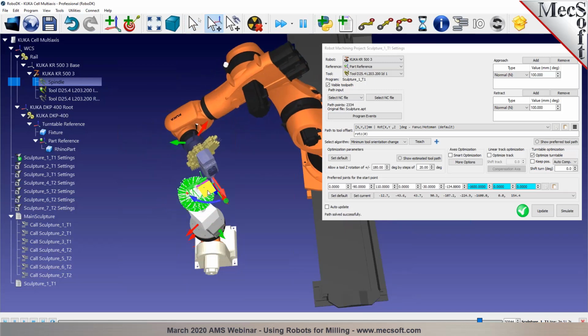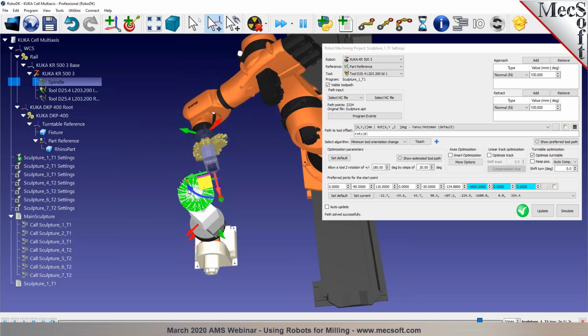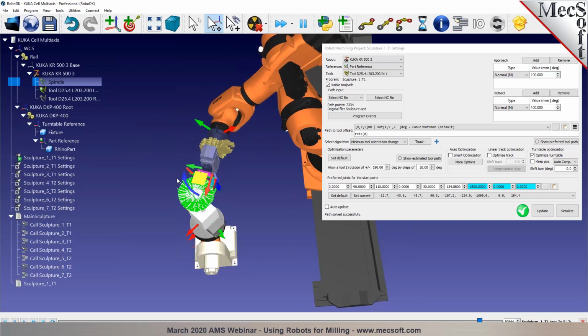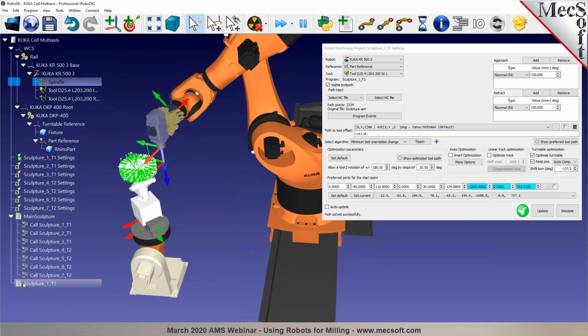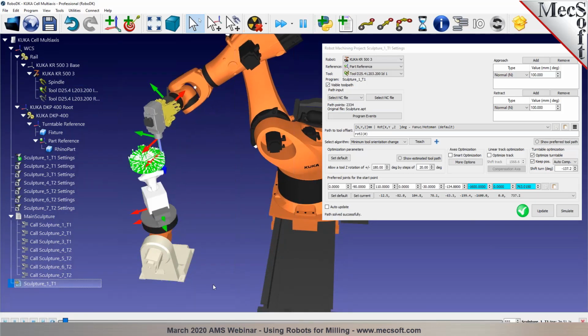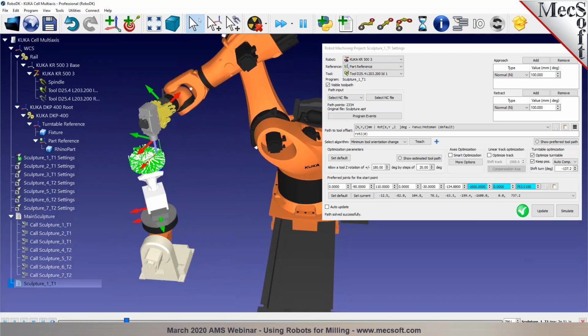With the Alt key, you can move and say, for example, we'd like to be working more with an orientation that looks like this. So you could select Teach, and all these settings. So compared to previous setups, now we can see additional settings here to manage external axis. By selecting Teach, those settings have been automatically changed to accommodate this preferred orientation. As we update, we're updating this program. We can double click or simulate to see what it is that it wants to do.